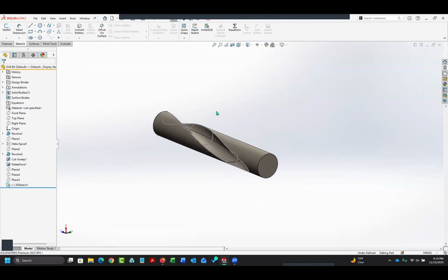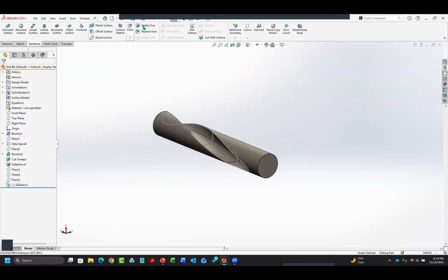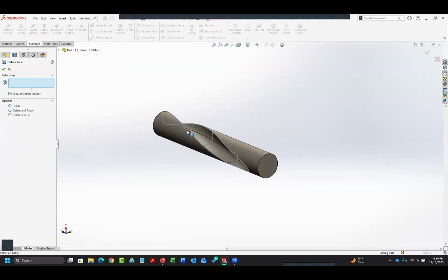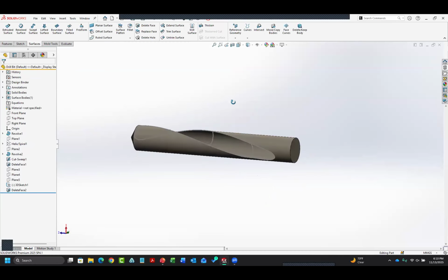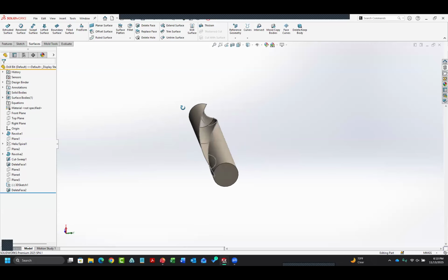And so I have almost like a replication of kind of the fundamentals of my geometry, but a little bit cleaner. So I'm going to just delete those faces that I know are bad. Let's just delete them out. The delete face feature in SolidWorks is really the only feature that converts a solid into a surface because it makes it no longer volumetrically airtight or watertight. So this is now completely open, just a set of surfaces. But all my sketches are there because of how the SolidWorks tree goes from the top downward.